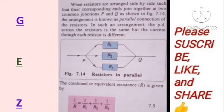Now the combined or equivalent resistance is given by 1 over R equals 1 over R1 plus 1 over R2 plus 1 over R3. So this is simply the addition of the reciprocals of the different resistance values, and then you are going to look for the reciprocal of your corresponding answer. So that will be your resistance in parallel.